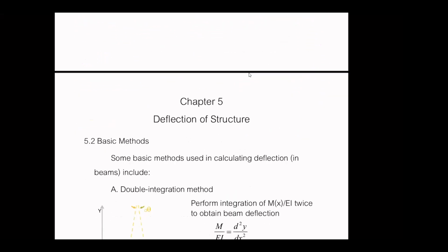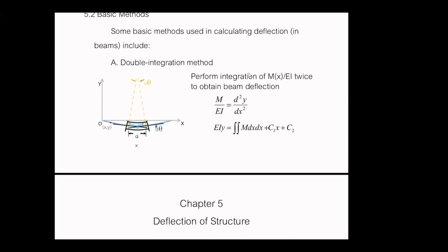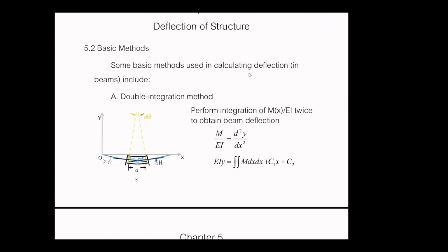All right, let's talk about this a little bit more before we have another break. We have so many methods to calculate the deflection. You have learned the double integration method, where you write your moment equation and perform integration twice, and you get the general equation for the calculation of deflection anywhere on your beam. This is a good method, very quick, but it cannot be used to calculate deflection in the frame.